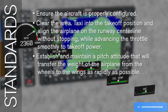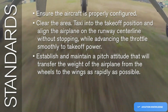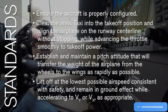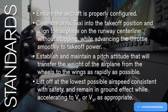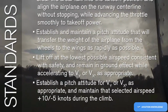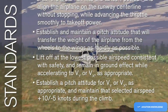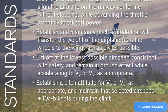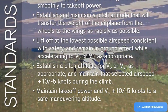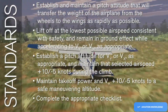Establish and maintain a pitch attitude that will transfer the weight of the airplane from the wheels to the wings as rapidly as possible. Lift off at the lowest possible airspeed consistent with safety and remain in ground effect while accelerating to VY or VX as appropriate. Establish a pitch attitude for VY or VX as appropriate and maintain that selected airspeed plus 10 or minus 5 knots during the climb. Maintain takeoff power and VY plus 10 minus 5 knots to a safe maneuvering altitude. Complete the appropriate checklist.